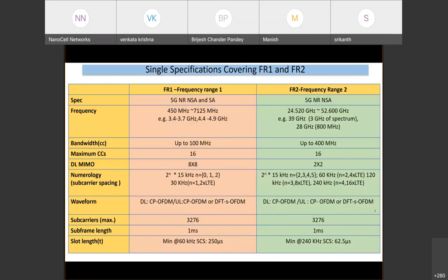Okay, so let me try and give an answer, given it's an overview session. Just try and address your point. So the user doesn't choose FFT, etc. The implementation chooses the subcarrier spacing. For the subcarrier spacing choice, we gave a few examples, right? Typically, there are constraints of macro cell, small cell, high bandwidth, low bandwidth. These are the constraints that typically dictate what subcarrier spacings you use.